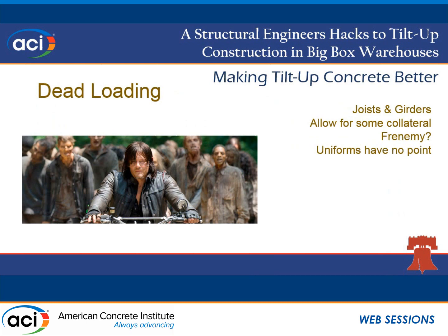Dead loading, as I talked about a little bit in the seismic loading, sometimes dead loading is your friend, sometimes it's your enemy. So when designing big boxes, I always carry kind of 3 different loads. I've got the design load for the girders, I've got a design load for the joists, and then when I'm backing into what's my uplift to design my footings, I have the real load. So usually I account for 3 to 4 to 5 pounds per square foot of fire sprinkler, so that way when the fire protection guy gets in and actually does the design 2 months after your steel's already been reviewed in shop drawings, you don't have to go back and figure out how to retrofit for every 2-inch and 3-inch line. But you got to understand that while you've upsized the joists and girders for that load, it's not actually there. So when you're checking your footing, make sure that you've accounted for what you expect to be there.